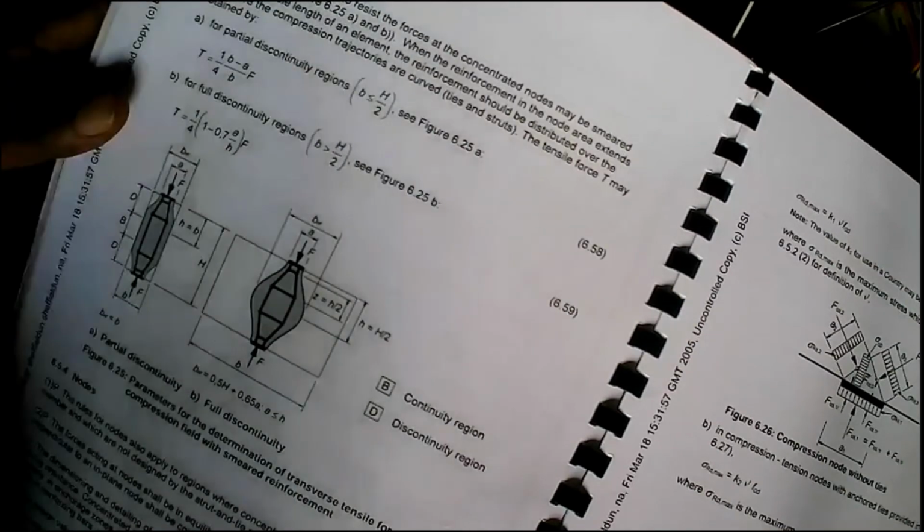But what actually happens is, because we have a pile cap which is fairly large, and also because we have the reinforcement at the top and bottom and also on the sides, generally we do not try to provide this. There's another reason, and that is, we get the column reinforcement also continuing to the bottom, and also pile reinforcement continuing.